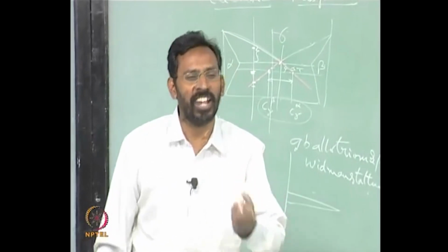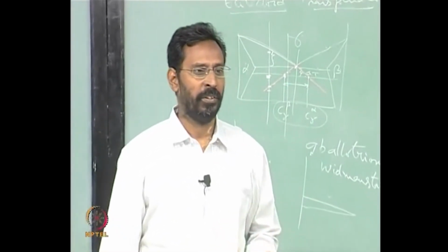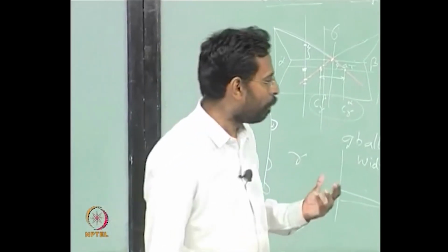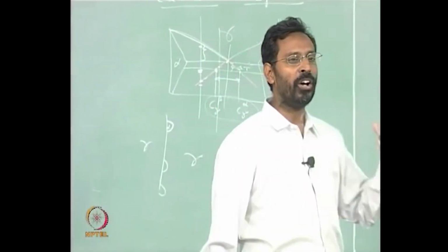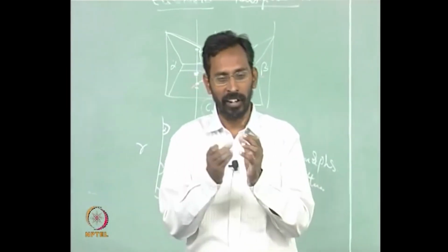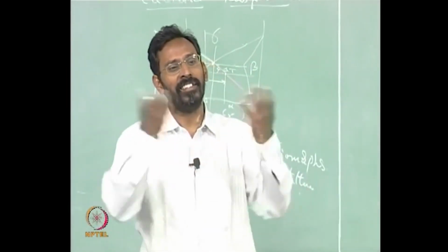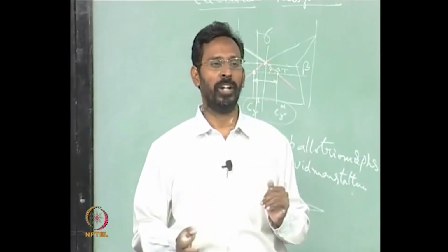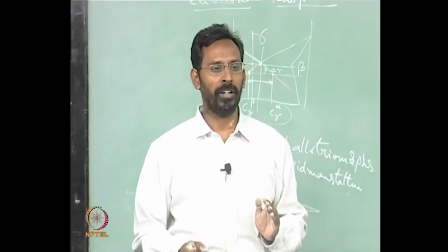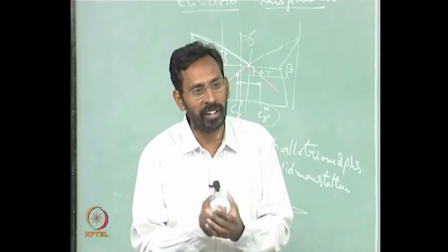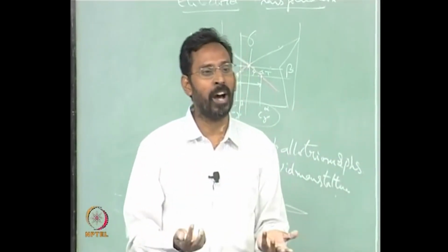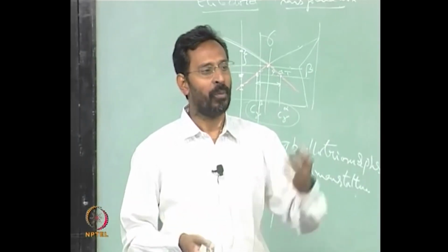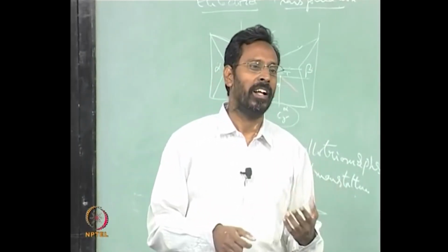You have to consider the strain also here, and particularly because there you are talking of nucleation of the cementite inside the liquid, is it not? The symmetry, if you consider a eutectic composition, let us say 4.3% composition, it is forming inside the liquid. Here it is forming inside the gamma. If it is forming inside the gamma, then you need to consider what that interfacial energy is.